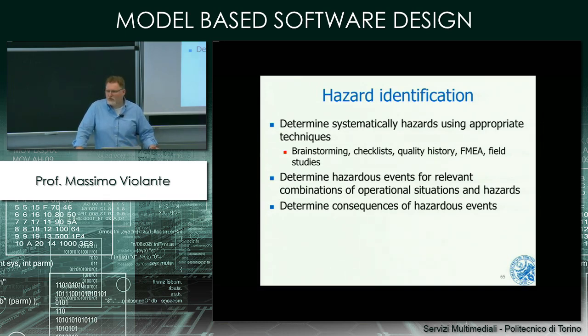If we were using the ultrasonic sensor as a radar, having no distance is a problem for sure. We cannot provide any measurement. Having a false distance that is considered higher than what it actually is is a very big problem, because you are assuming the object is much more distant than what it actually is.